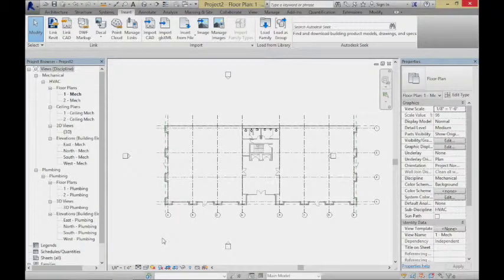What I'd like to do is put some grids into my model that reflect the structural grids that I've already put in the architectural model. I could just create some new ones right on top and have my own separate little grids, but I'd actually prefer to have some grids that were a little bit smart about this. So if the architect ever decided to move his grids, my grids would move too. I'd like them to stay in sync with each other.